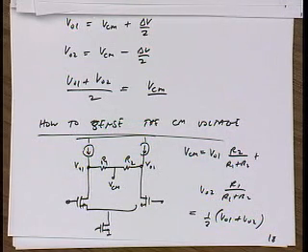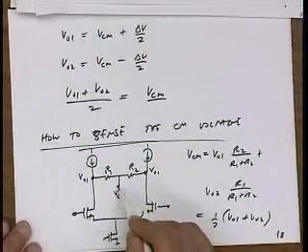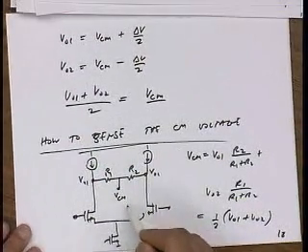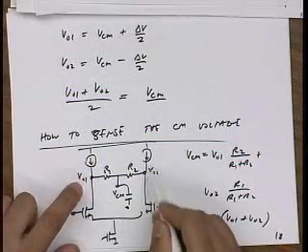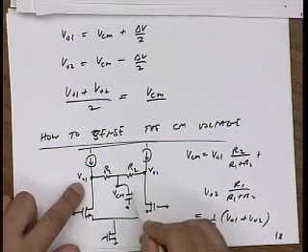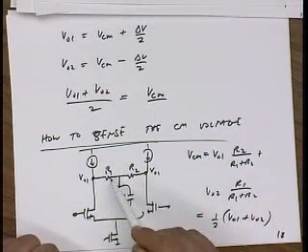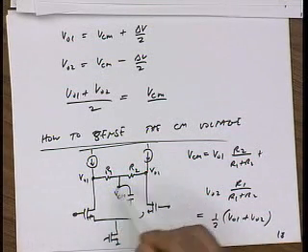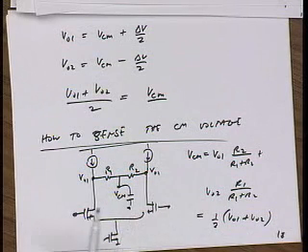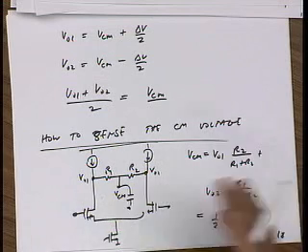Well, the problem is speed, right? I mean, you alluded to it with it's going to not only load the differential, but at this common mode voltage, there's got to be capacitance, right? And that capacitance doesn't hurt our differential mode output, but it will slow down our common mode output. The time constant for this common mode detection circuit is R times C. So if R is too big, then the common mode slows down, right? If it's a giga ohm, it doesn't take much capacitance here to have second time constants, right?